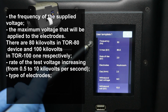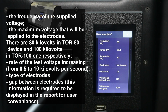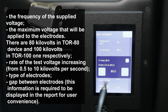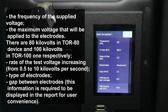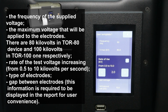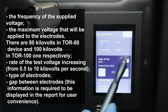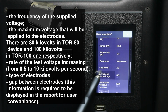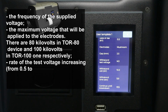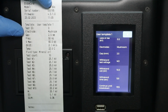The frequency of the supplied voltage, the maximum voltage that will be applied to the electrodes. There are 80 kV in TOR-80 device and 100 kV in TOR-100 respectively. Rate of the test voltage increasing, from 0.5 to 10 kV per second. Type of electrodes, gap between electrodes. This information is required to be displayed in the report for user convenience.